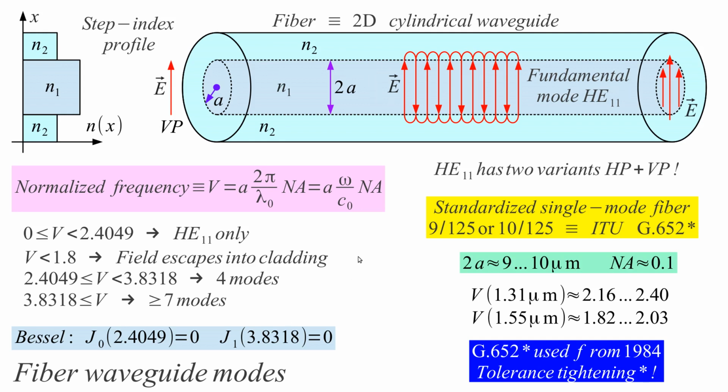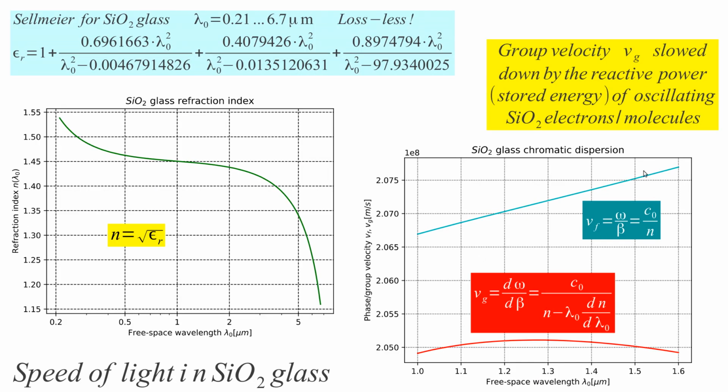When we're trying to make better use of our fiber, we get into problems with material. Those 4 terahertz are not that easily attainable, because glass changes a little bit its refraction index over our wavelength range. At the shorter wavelengths in ultraviolet, we have UV resonances.